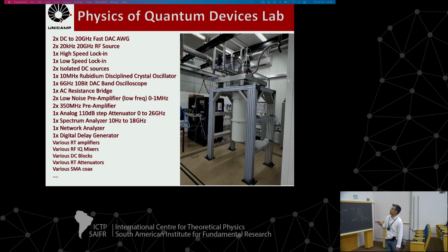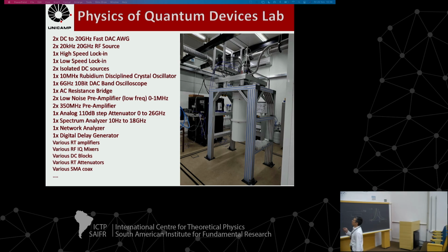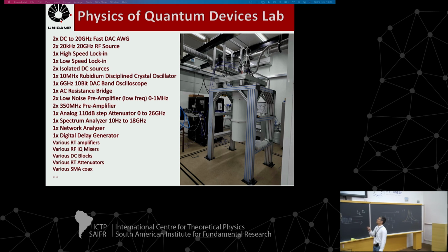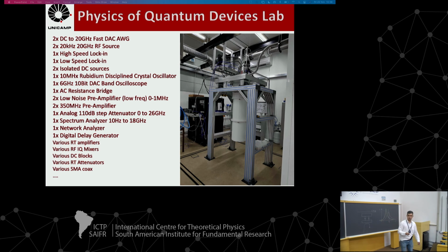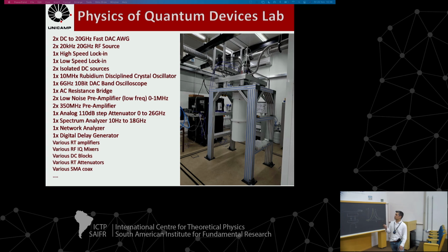Also, I don't have any direct connection from the rest of my lab with this circuit here. So this is electrically isolated from the rest of the system. We also have a ground that's specific for this system, in the middle of the lab, not connected to the rest of the building. So if I need to ground this system, I can ground it in a ground that's not connected to any other machine. Okay?